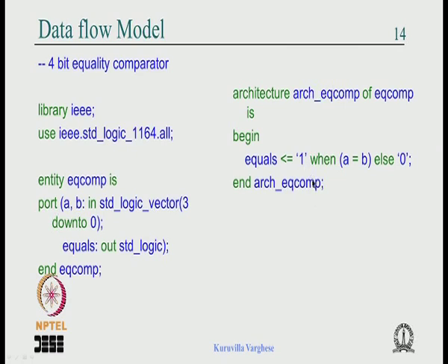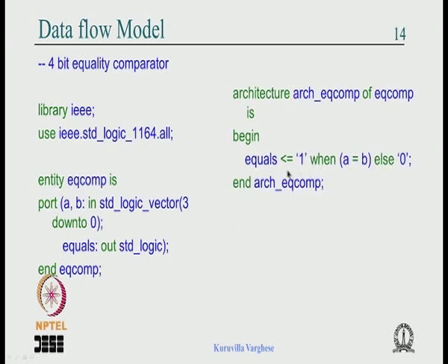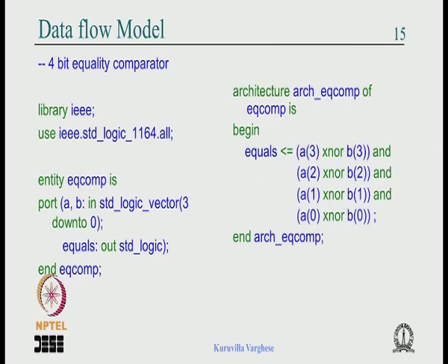So if you ask me whether the when-else or the equation is better, then definitely this is much more concise, and we will see that for the tool, this will generate exactly the same circuit as that, and we will see how the synthesis tool generates the circuit out of the description.